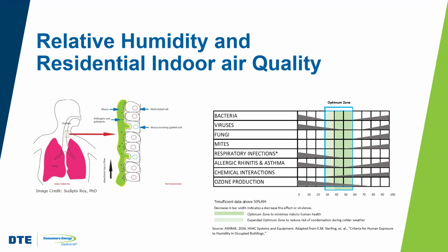And that may be the best that you can do with the HVAC system that you currently have in place. But know that the goal should really be to achieve higher relative humidity levels, right? To get it up between that 40 and 60%. And that may mean that we need to do things differently with the house envelope, which we've talked about in previous webinars,